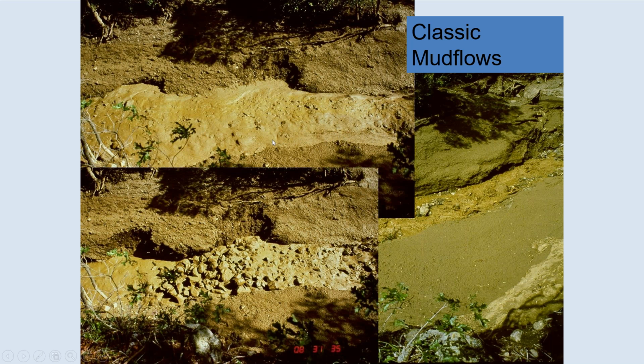One of the things to note when you see a mud flow is that there's a very clear shear zone that occurs if you look down upon it. Now, this shear zone will occur throughout the flow event, and it'll make it more U-shaped. The actual flow inside the channel will become more efficient by making this U-shaped, and you'll see the shear zone occurring along the surface here, but it's actually under the flow, and the flow in the interior often becomes mounded a little bit. So these shear zones become important.